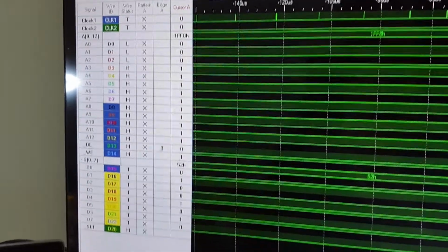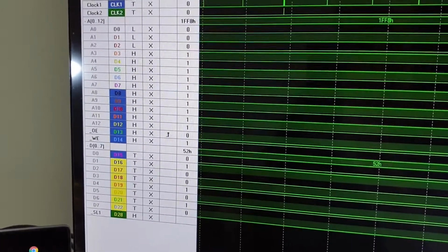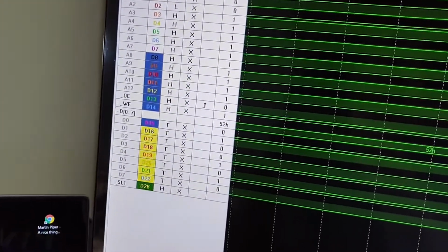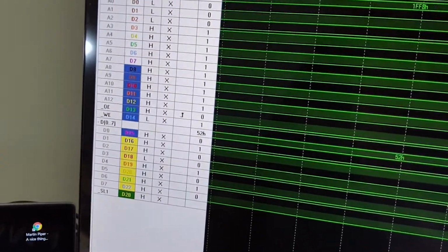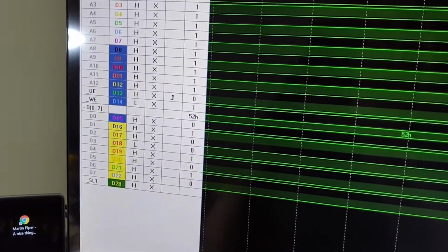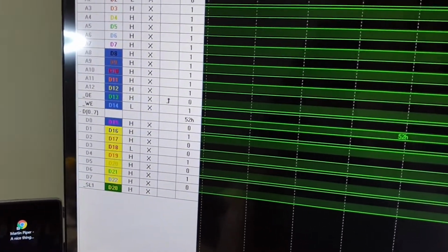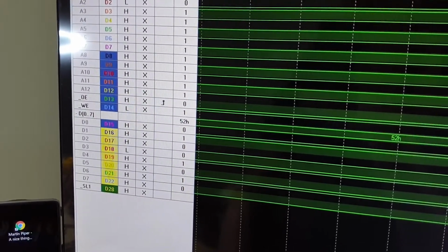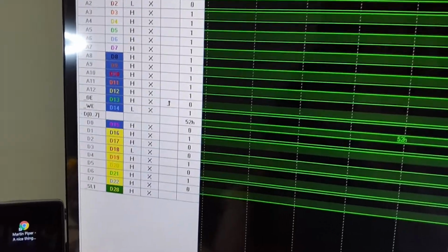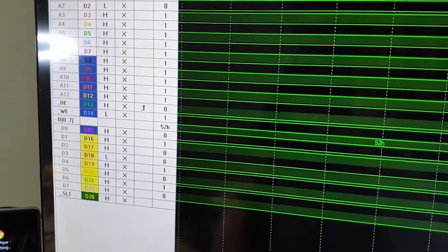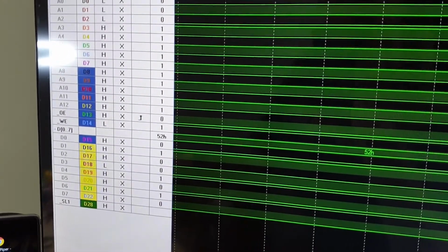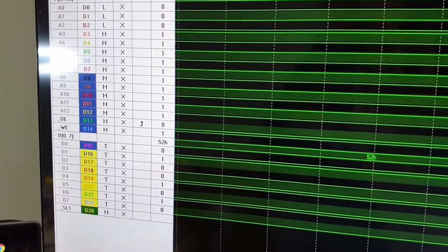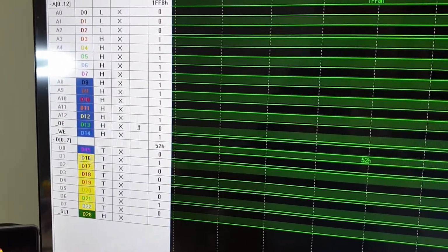So then, because it now switches in, because it now disables the output enable, it's gone high, you see, but there's no write enable yet until I set the write enable down to be low. And then if I set the write enable down to be low, then I can see that I'm writing, or the memory bus going now into the RAM, because it's write enable low. The pattern is high, high, high, low, high, high, high, high. That's kind of like one pixel in bitplane data being activated there. So then I set it back to be not write enable mode. Okay, like that. And then the data bus goes into a transient or high impedance state, I think.